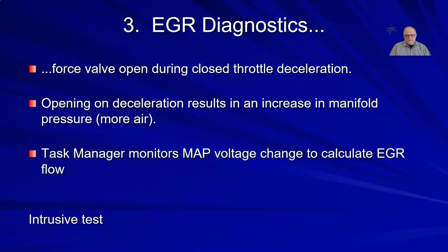Third test. On this test here, during a deceleration, we're going to be going from 55 down to 20 or 60 miles an hour and decreasing. Your foot is off the throttle. You're not hitting the brake. No AC, no rear defogger turning on or off. While you are doing what most people call compression braking, you're not actually compression braking on a gas engine. You're actually vacuum braking.